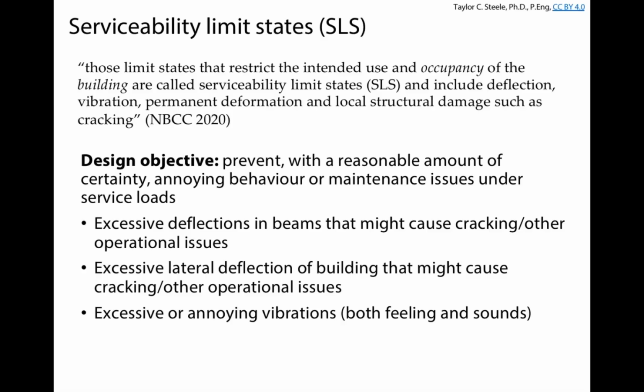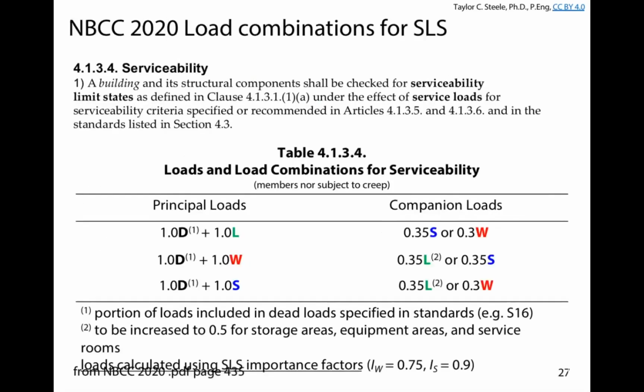What I'm trying to communicate here is we're applying load factors to things we want to have happen in the absolute rare circumstances, which is death or injury or significant injury. Other things, cracking of floors or walls, not very important, right? So we're going to accept the fact that those are going to happen more frequently because they're more maintenance issues than they are personal injury issues.